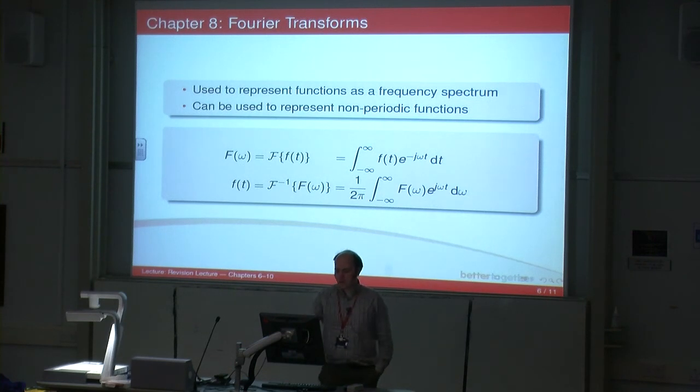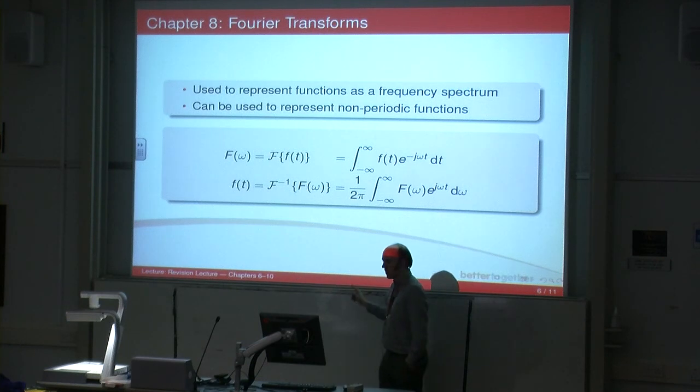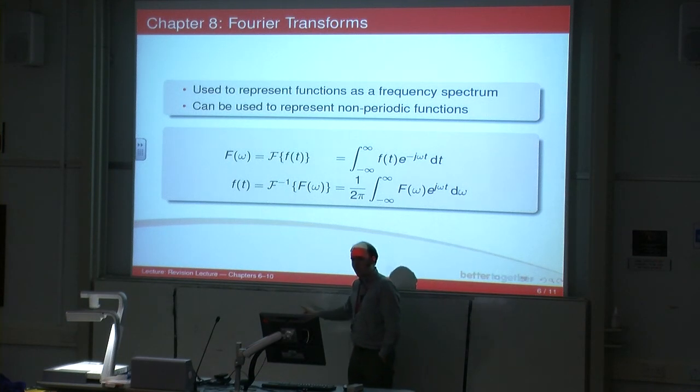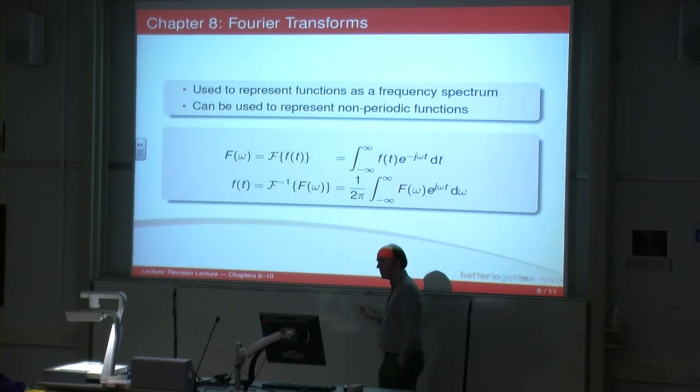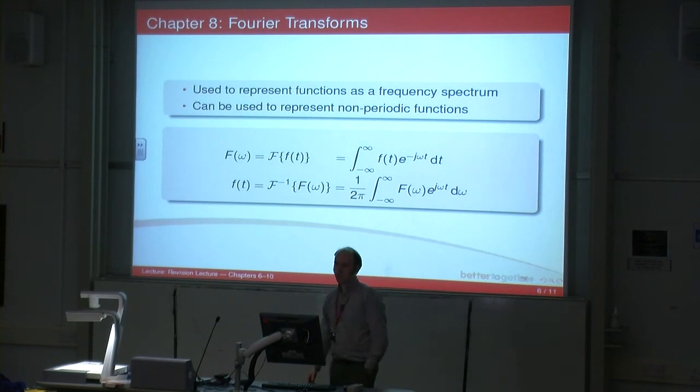Now we actually did Fourier transforms back in chapter 4 when we were looking at Fourier series. If you plotted along the x-axis all the different frequencies, so omega, 2 omega, 3 omega, and so on, and you plotted up the y-axis your values for an and bn, you had a bunch of lines. All those values were a frequency spectrum representation of a periodic signal.